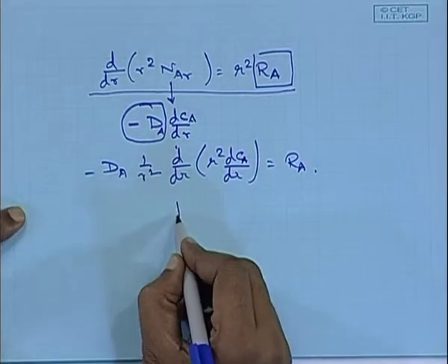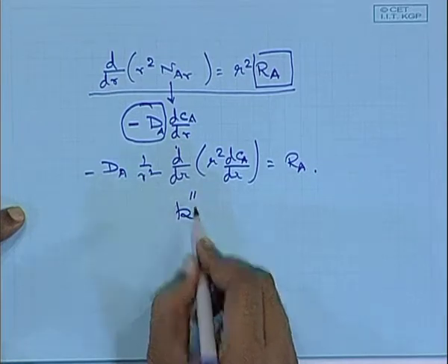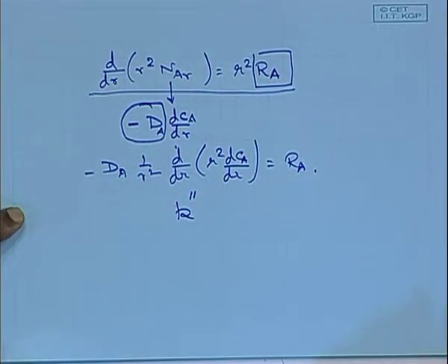So, I know that RA has to contain K double prime. So, this is on a per unit area basis. Now, the reaction rate per unit area has to be converted to per unit volume, and when I would like to convert it to per unit volume, the concept of active area of the catalyst per unit volume would come into picture.